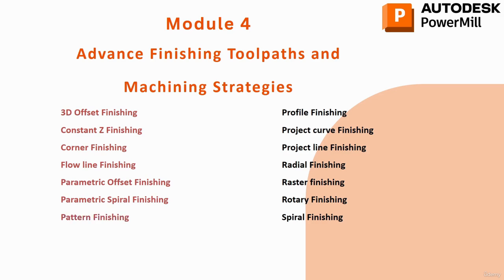As you know, in the pattern finishing operation, we just have to follow the pattern. The cutting tool follows the pattern, and according to the pattern, the cutting tool performs all those things which we need. The depth of cut, the step over and step down, and the merge will be done in this operation. You can do multiple cuts using the step up and step down settings. So that's it for the pattern finishing.